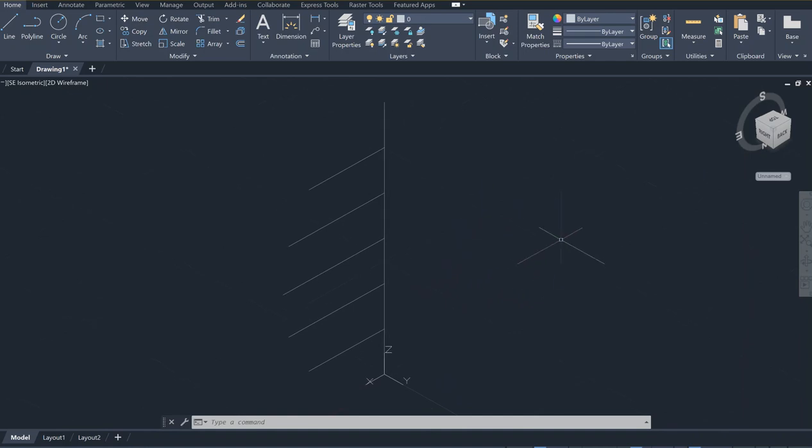Okay, so what are we doing? We did the user coordinate system, we adjusted that. We did the trim command, everything is done. Extend command, we've done this one. Orbit command, we did this. Now there's a command called rotate 3D. There are two commands regarding rotation. One of them is rotate 3D. It's a beautiful command. It enables you to rotate objects in the 3D world. So I'll take rotate 3D, enter. And what are we rotating?